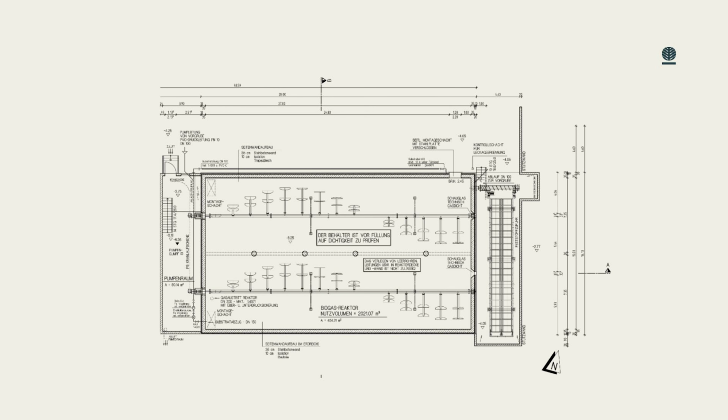It is because of the agitators. We built the digester around the agitators, and as long as they are running, we can homogenize and mix the substrate all together. So we push up sediments and we push down floating parts, and so we mix everything into the sludge inside the digester.